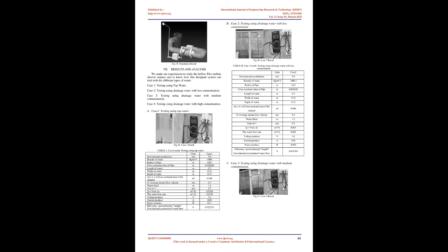A circular pipe is inserted between two stationary pipes, with their axes on a line. The inserted pipe is supported by two bearings, so the pipe can rotate around the central axis. A runner is embedded within the inserted, rotational pipe. When water flows in the pipe, the runner and the pipe rotate integrally around the axis. A guide vane is mounted at the end of the stationary pipe, just upstream of the rotational pipe.